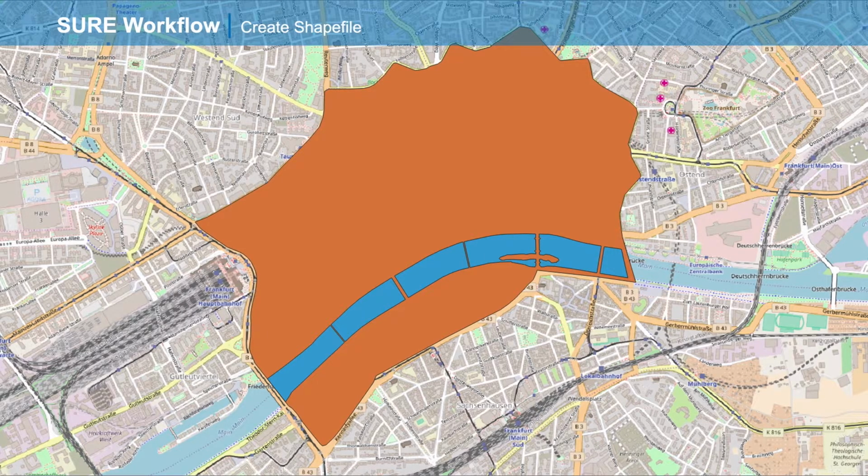On the other hand, we can feed water shapefiles to the software to tell it where in fact there is water, so we can also treat the data in a different manner because we already know that it's water, and we will create clean looking water surfaces from this shapefile information that is fed beforehand.